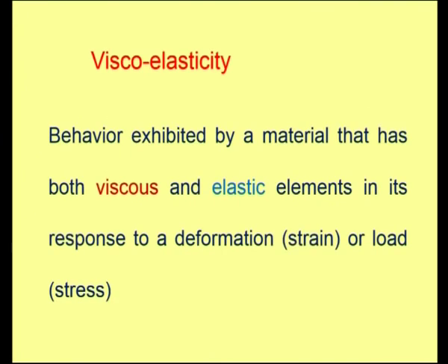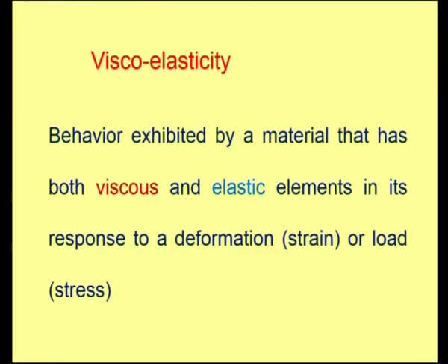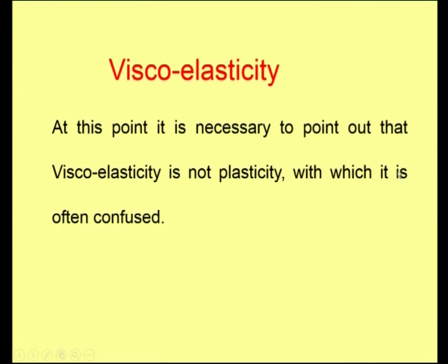A quick recap on what is viscoelasticity. It is a behavior exhibited by a material that has both elastic and viscous elements in its response to a deformation or load. At this point, it is necessary to point out that viscoelasticity is not plasticity. Most of the time people think that viscoelasticity is just the opposite of plasticity. It is not the case.